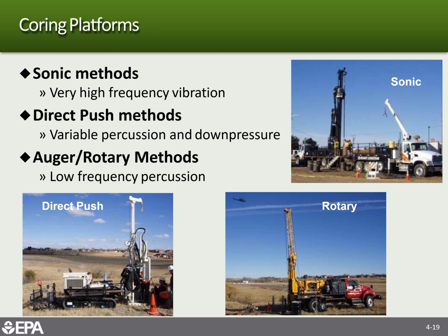So what are the methods you normally use to get cores? For deeper zones, sonic seems to be the best. For unconsolidated zones, I've collected sonic cores down to 200 feet before.